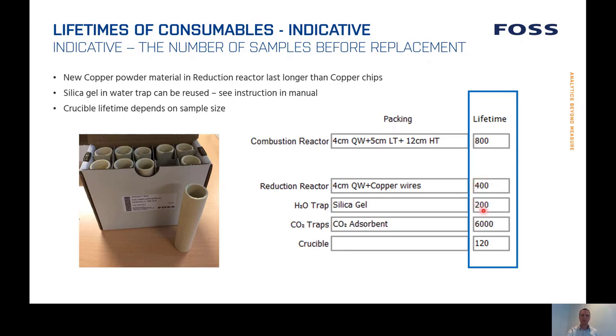You can visually see that if the silica gel is pale, then it doesn't work. And you can also see it in the plot and the integration, where the water is popping up. Then you need to regenerate this silica gel.